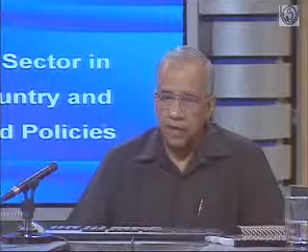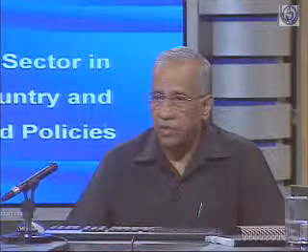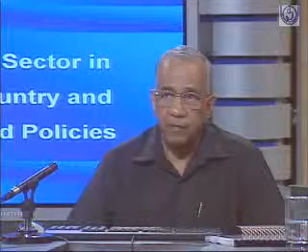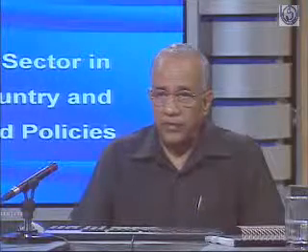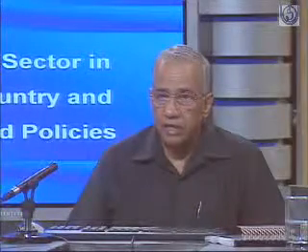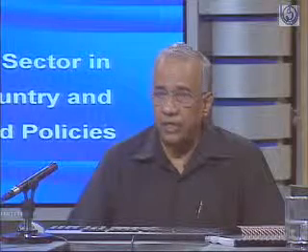But 50 hertz or 60 hertz has nothing to do with the efficiency of generation. It is one system adopted in the country, and Japan has 60 and 50, and there are many countries who have different frequencies in different parts of the country. The reason is not that they could not generate at 50 hertz, but at some point of time there must have been compulsions of importing machines of a particular design to operate in that area. The interconnection of grids is very important. If the grids are to be interconnected, then the whole grid has to operate at one frequency.